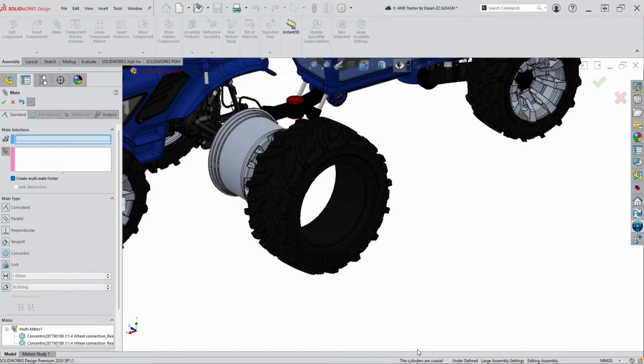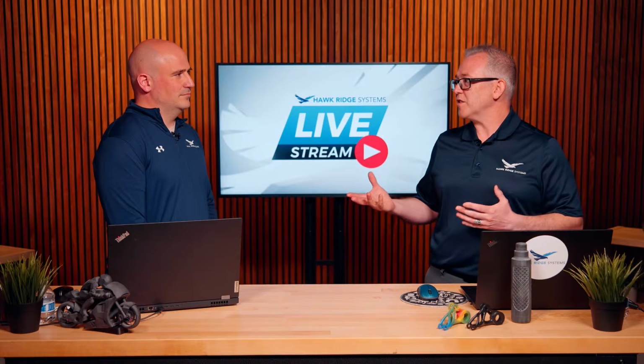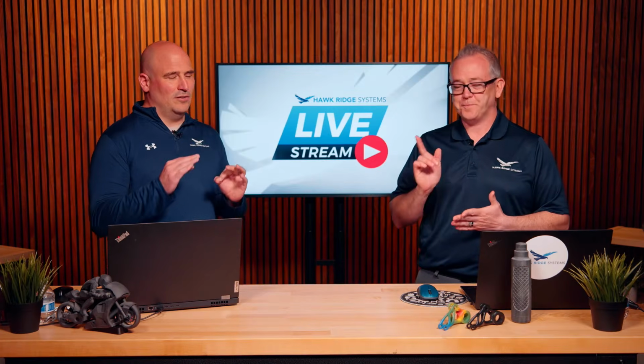Yeah, that's a great point. If you don't need multiple mates to do the job, you get it done with a single mate, it cleans up the feature tree, makes things a bit faster. Remember that all mates are non-linear, solved inside of the assembly all at the same time.